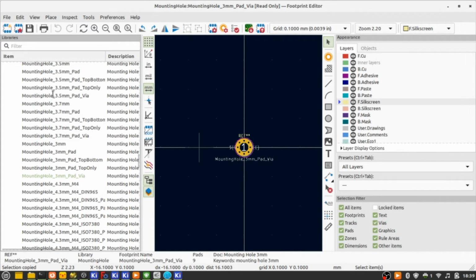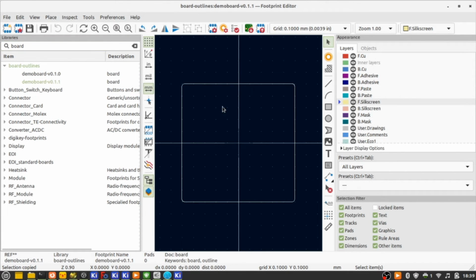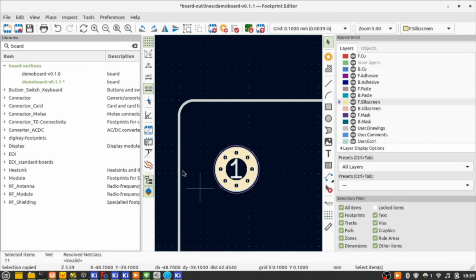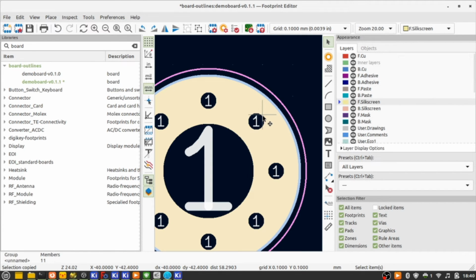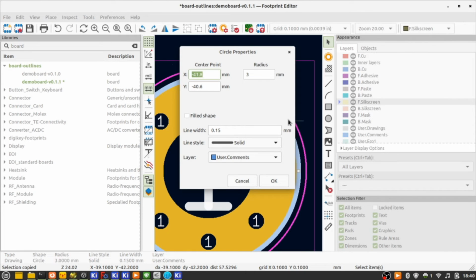So we can just take this and copy it directly into the footprint that we're designing, and it just copies everything. I do not want any labeling, any reference designators, or anything attached to that footprint. And I want to group it because each one of the vias is its own part, as well as the top pad and the mask settings.